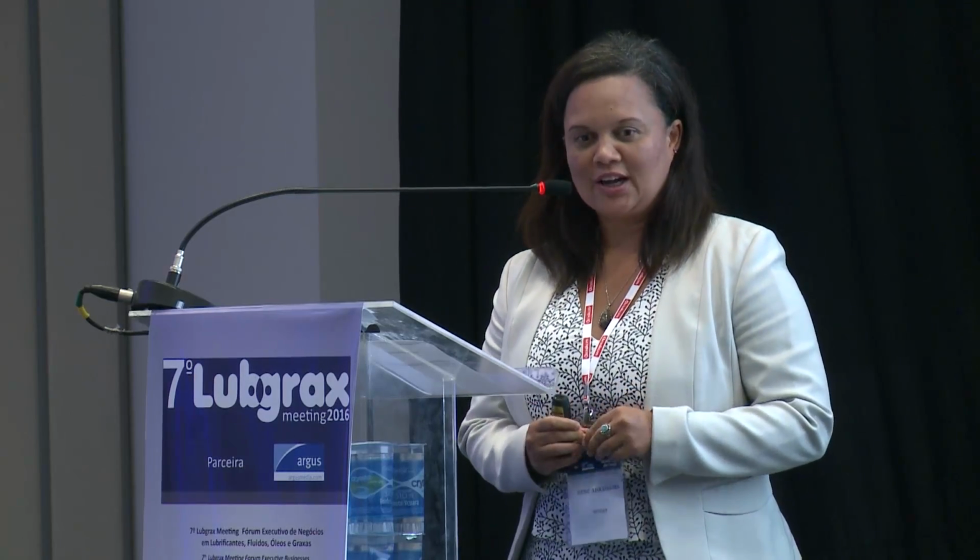Right, so first, it's maybe a bit difficult to see with the different colors, but here we have the storage modulus and the complex modulus. Grease is a viscoelastic kind of material, so this represents the viscous part, which is usually the top curve, and the elastic part, which would be the lower curve on each graph. Then we have this viscoelastic region, so you want that to be as long as possible, and as your grease is sheared, you expect some softening, but you don't expect that much softening, so you want it to be stable or hold out as long as possible.